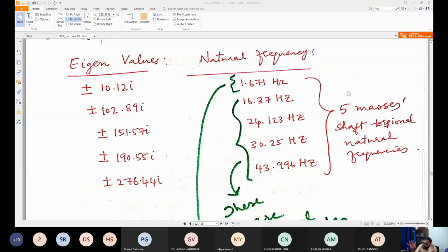And if all the 5 masses are considered as a single unit, twisting with respect to the system that the whole group of masses is connected to, there is an oscillation of the whole mass as a single mass, as a center of inertia mass, against the system. So that is the common mode, and all others are torsional modes.